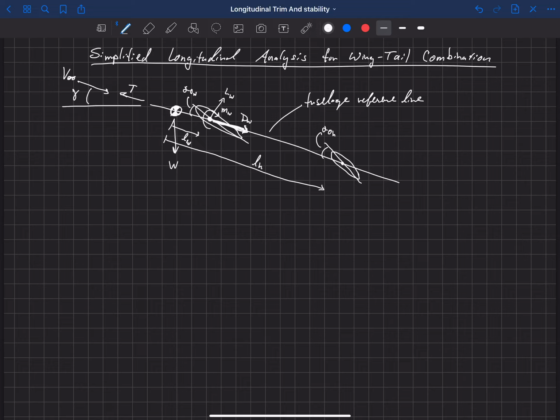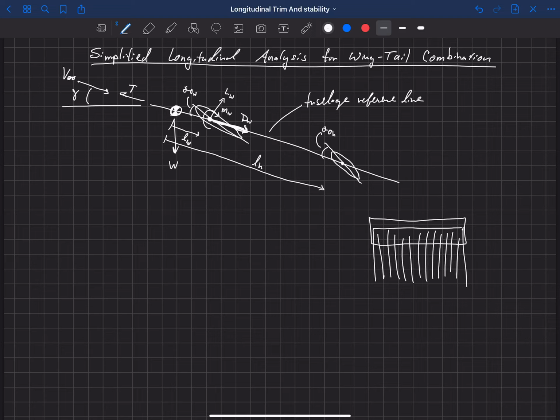Now, before we discuss the forces and moments on this tail, we have to understand one important thing, and that is that the horizontal tail is flying in what's called the downwash of the main wing. So if we go back to just wing theory, we understand from a top-down view that the aerodynamics of a main wing can be modeled by the system of vorticity, and we have downwash along the lifting line there. We have downwash coming from this sheet of vorticity back here. So everything is pushing the air down in this region, and now we've got a horizontal tail sitting back here in this region.